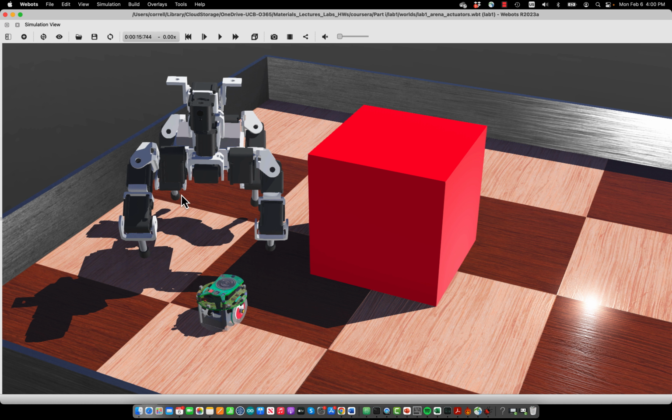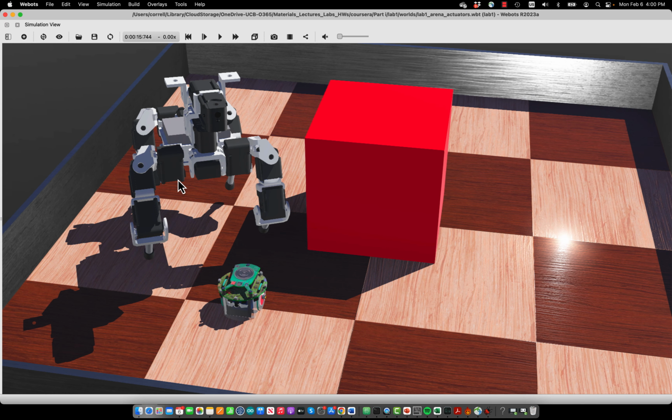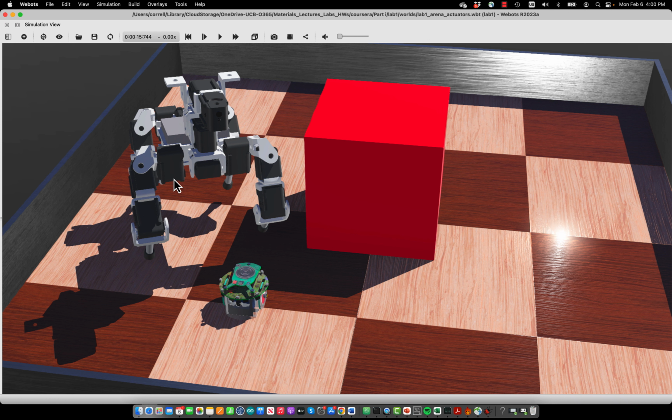In this Bioloid example, the servos are made by Robotis, which is a Korean company, and called AX-12. They use DC motors inside, and they don't use an encoder, but simply a potentiometer, which measures the resistance and allows the controller that is inside the servo motor to determine its position. The AX-12 motors also have a digital microcontroller, which allows you to set the position and the speed, and sometimes to even control the torque of the motors by regulating the current, which makes it a very sophisticated system.